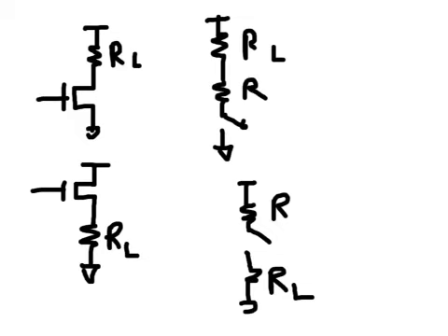Conceptually, these 2 circuits function the same way. They look similar, but there are important differences in the way they function. Remember that the NMOS relies on a positive voltage to create a channel, which then acts to close the switch and provide a conducting path for current.